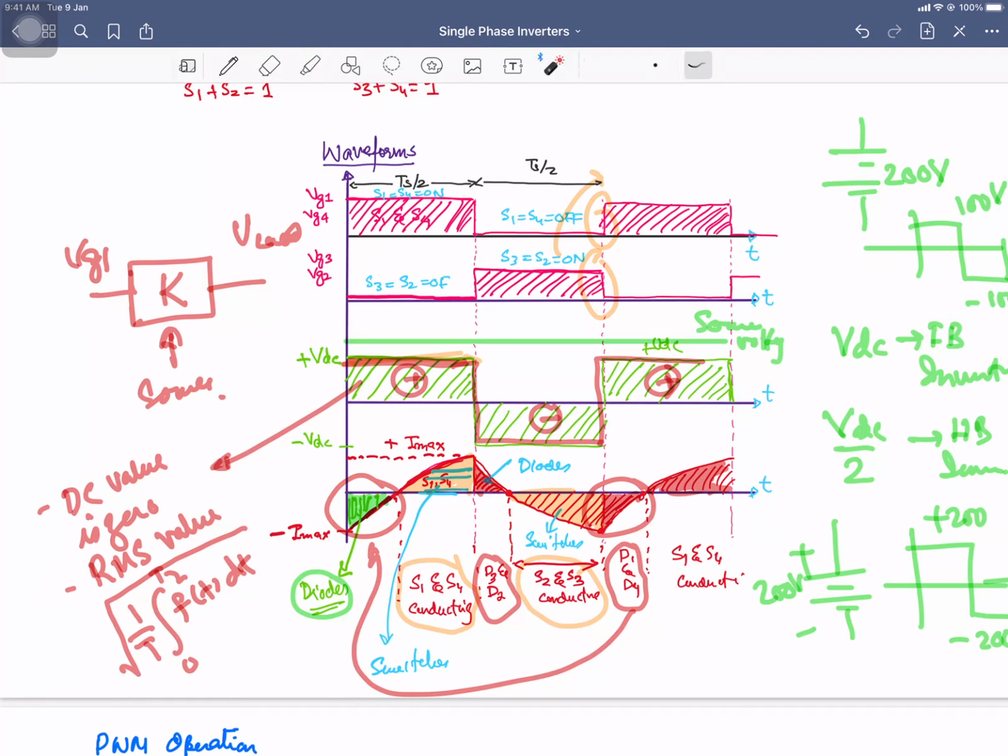For the RMS value, as you are going to take the square, the positive part is already positive, it will become more in magnitude, and this negative voltage is also going to become positive. So if I sketch that, I am going to get only the positive area, right? When you take the square of this part, it is also going to become positive. So the whole waveform is going to become positive, and that represents just like the effect of the DC.